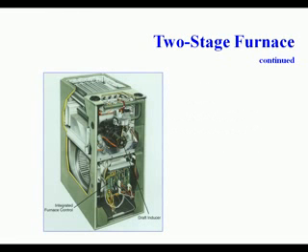Two-stage furnaces are becoming more popular as well. They feature 2 levels of heating. It adjusts between high and low fire to meet demand. The majority of operation is in the first stage, or low heat. The low heat stage requires less energy and offers greater efficiency and greater cost effectiveness. On colder days, the furnace moves to a high heat second stage. The motor adjusts automatically to meet the changing needs. Two-stage heating reduces the temperature swings and provides constant and comfortable temperature.